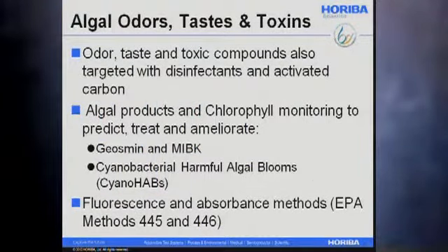So again, these odor, taste, and toxic compounds associated with the algal toxins are typically targeted as part of the disinfection and activated carbon treatment. And so monitoring these allows the treatment plants to predict, treat, and reduce the bad taste and odor compounds, typically known as geosmin and MIB, and other toxins.